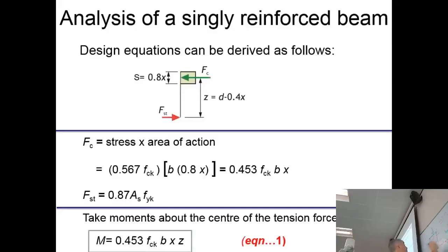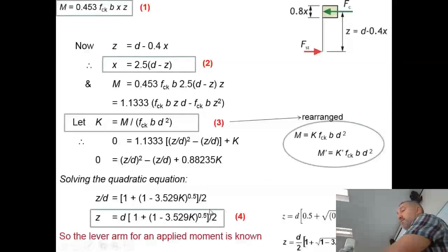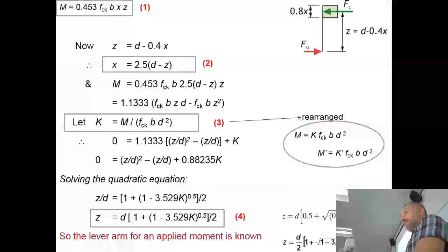So when I'm coming to design a beam, you've got the moment that's been applied via the action, and based upon these dimensions, I can work out what the moment of resistance, MR, is, based upon that formula there. It's a little bit clearer when we come to do some calcs.